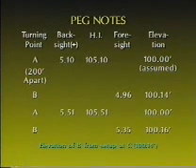Then, subtracting the foresight reading of 5.35 feet, the elevation of point B is 100.16 feet. Note that there is a difference of 2/100ths of a foot when comparing the two elevations for point B. This error is a result of the crosshairs in the level being misaligned. The error of plus 0.02 must now be removed from the level by mechanically moving the level crosshairs up 2/100ths to read 5.37 on the rod.